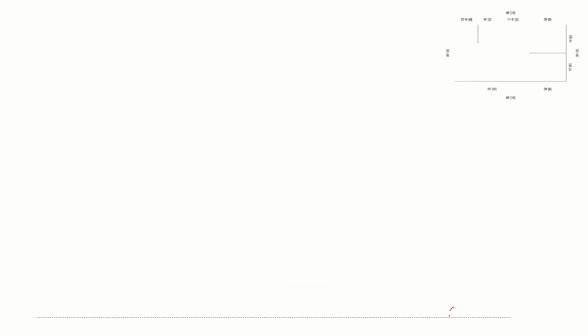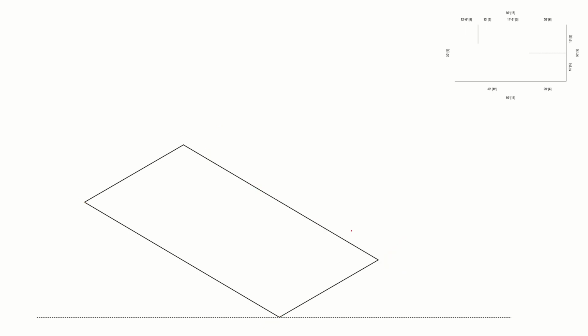Fine, quickly. So draw a ground line. Add a 30-degree line, add another 30-degree line. And add all the other parallel lines. I said in the beginning, you should make this as a guideline. You can have it as big as possible within your drawing sheet, and it can be guideline. First it can be guideline and then you can do detailing.